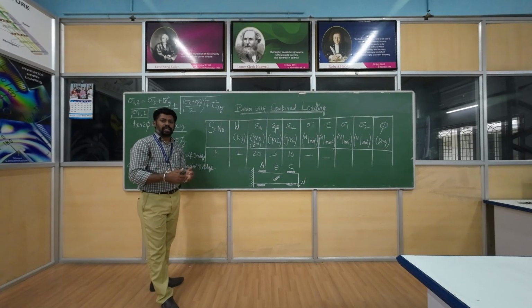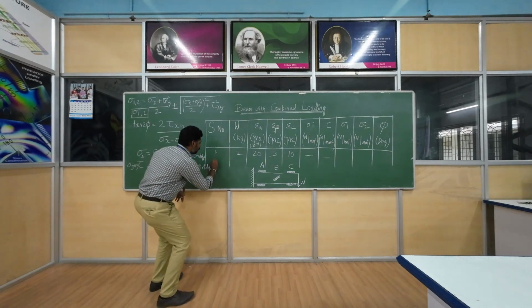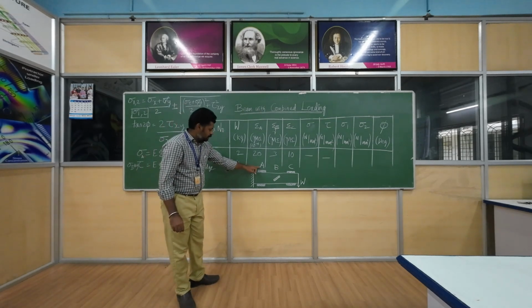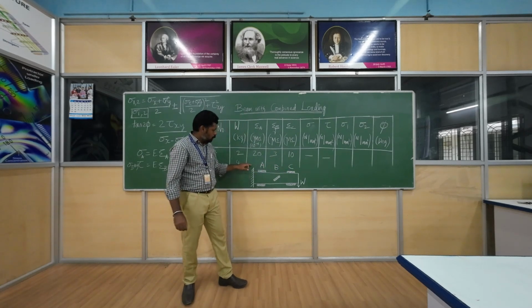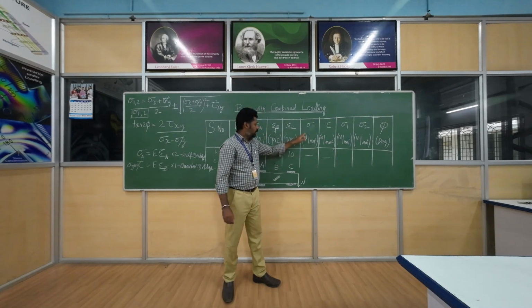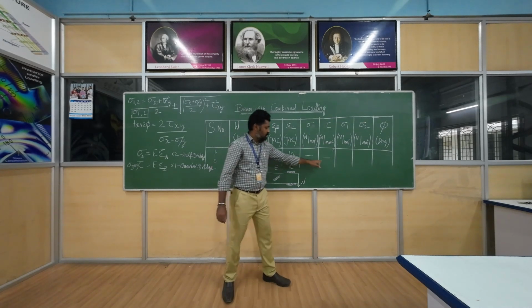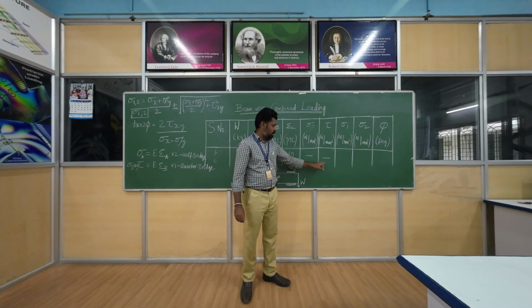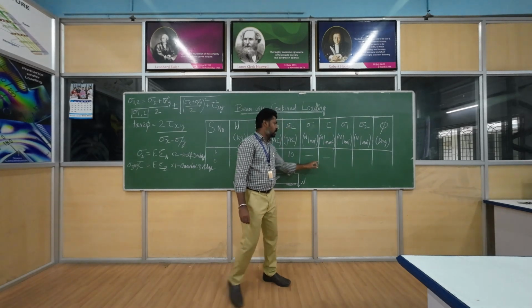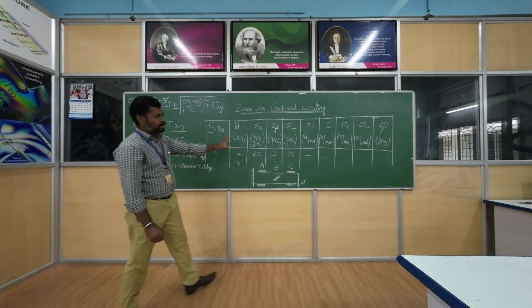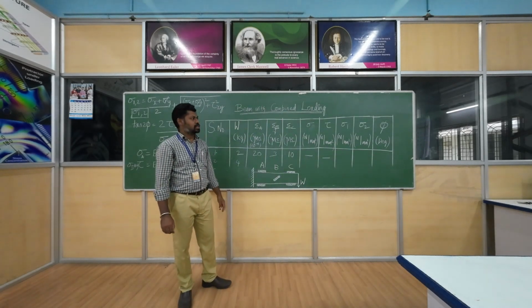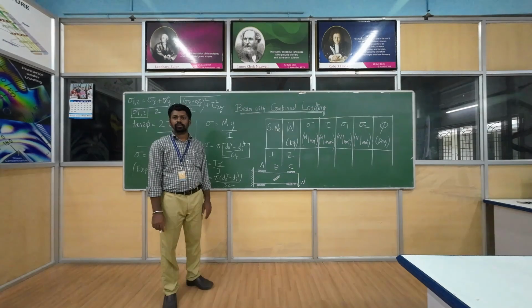Now we can do it for the second set of loading. So now add the load from 2 to 4 kg. Now measure the strain at A, B and C. Note down the strains. Now use the Hooke's law formula. Get the bending stress and the shear stress. Once you get the Cartesian components of stresses, apply these stresses in the principal stress equation. You get again the principal stresses. This way you can compute the principal stresses and principal angle for different sets of loading.